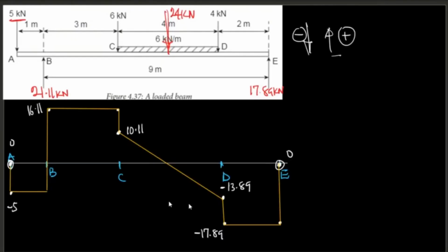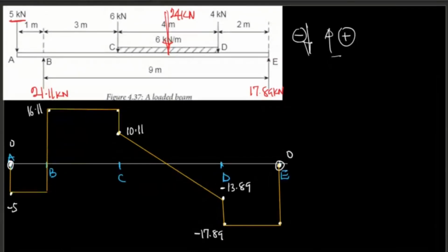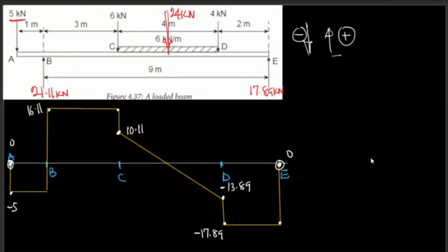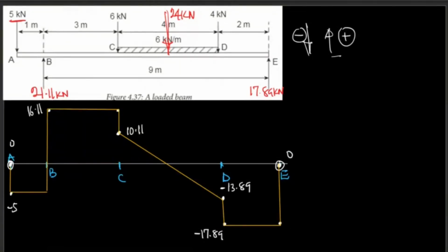Okay, so I told you that when you are doing your own diagram, your bending moment diagram must be directly beneath the shear force diagram. You must draw everything on a fresh page. Don't separate the diagrams. The reason why I'm separating the diagram is because there is no space here. So when you are doing your diagram, it must be on the same page. Make sure you use a full fresh page. You first draw the beam, and then you draw the shear force beneath, and then you draw the bending moment diagram just directly beneath the shear force diagram. Right?